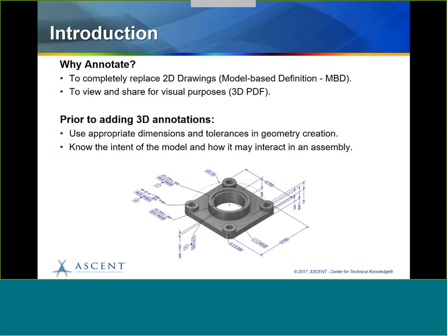By including all this annotation type information in your model, you're actually eliminating the need to create that 2D drawing for manufacturing. Some users might find that they don't want to eliminate the 2D drawing creation, but they still want to use 3D annotations to view and share the design. They may want to share them for verification purposes, that type of thing. A good format for that is using a 3D PDF. That's another export option that you have when you create your models and annotate them.